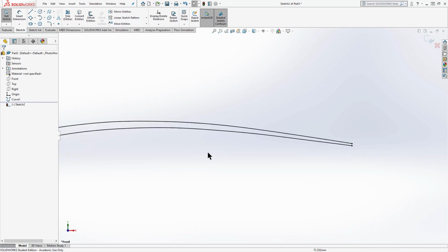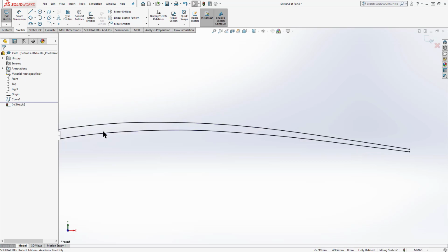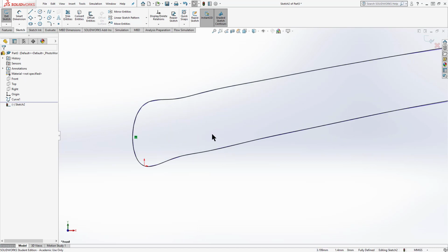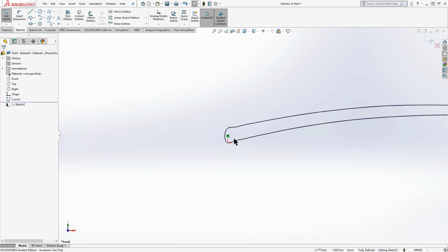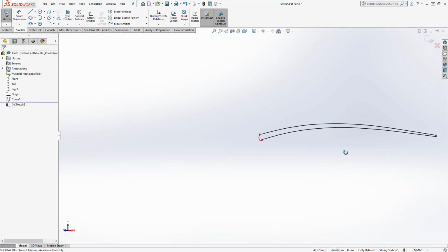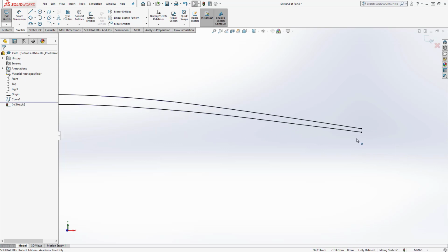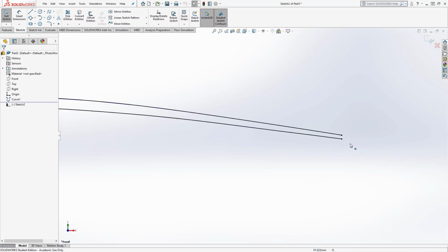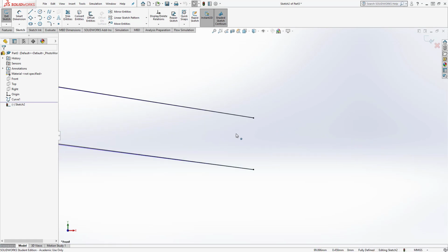But you'll also notice that it's not closed. It's all white behind here, and if it closes, it would be gray. So sometimes it's a little tricky to find where it's not closed. Typically, though, look at the leading edge, and you'll see all those points form a continuous curve. And I'm going to then look over here at the trailing side of it and zoom in. Let me just be sure I'm looking straight at it. And you'll see it's not closed.